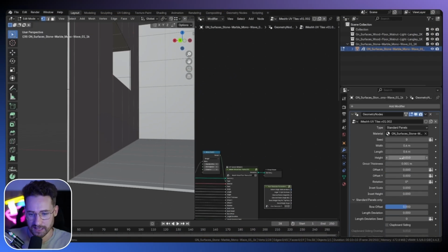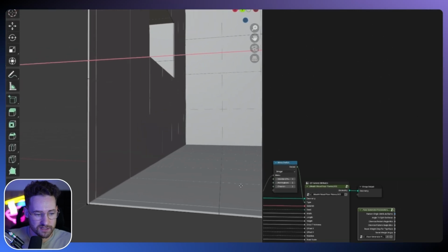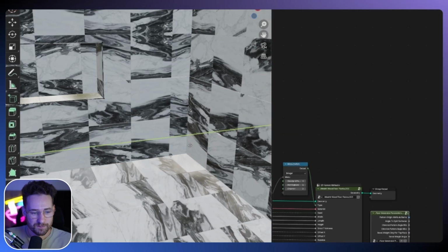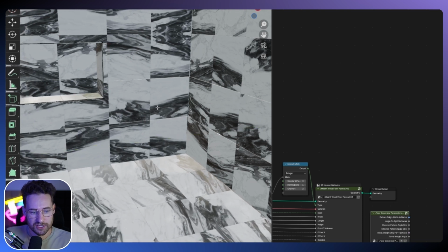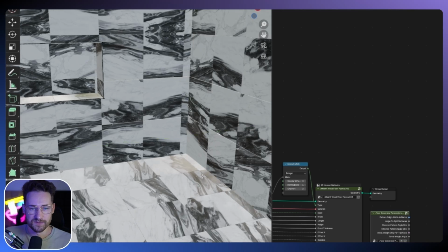They probably won't even be that thick, actually. They'll probably be quite thin. And you can then adjust exactly where the tiles are going to go. If you are making tiles and making a bathroom, please do remember that they should be like a full tile width apart, and they should ideally align like this where possible. If you have a half tile like this, it will generally be incorrect, and if it can align, then it should.